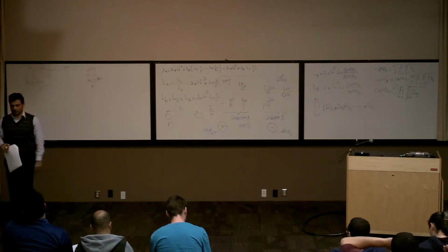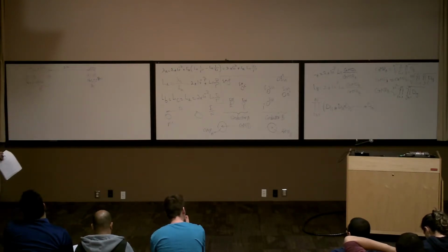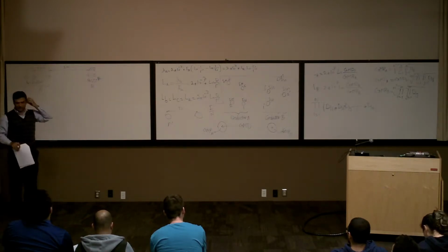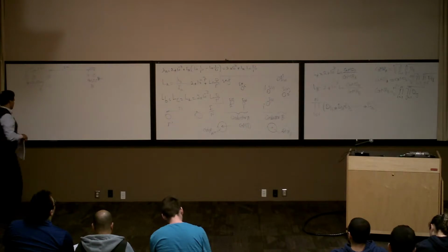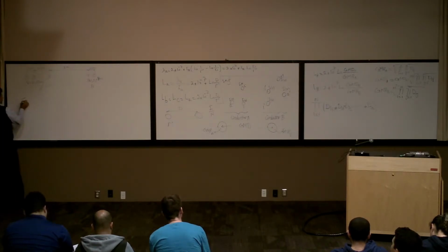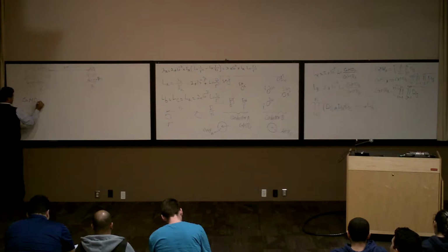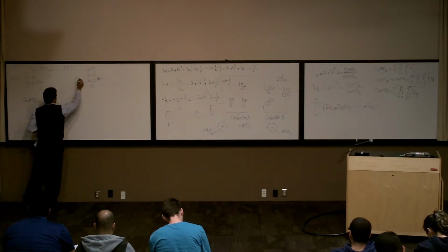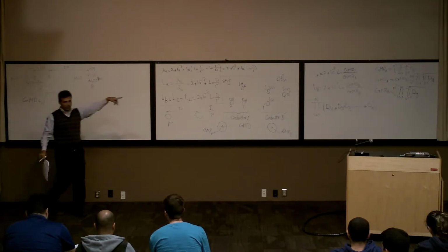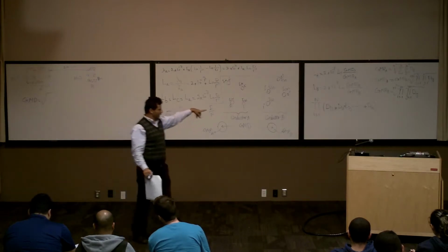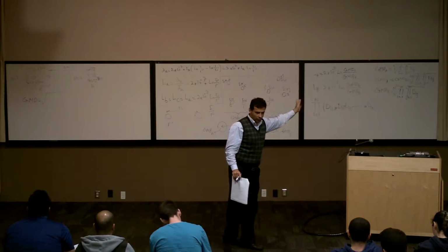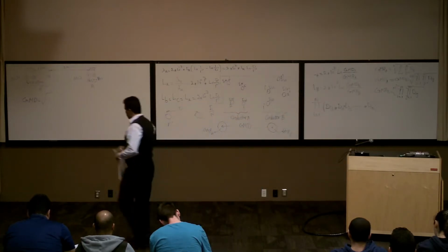Now I want to calculate the inductance of this system, LA and LB. Let's start with LA. Let's calculate the GMD first. What's the N here? N is 3, and M is 2. So based on what I put over there, the GMD is going to be the root of M times N, so 2 times 3 is 6, root 6